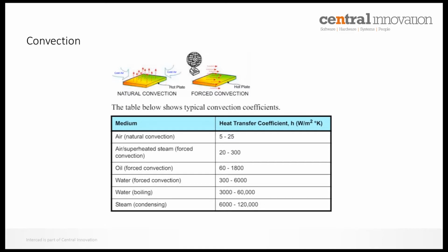In most engineering applications, when we need to cool down a certain surface or a certain body, we make use of a fan or a forced airflow or a heat pipe or a liquid flow, let's say a liquid cooling system, etc. What this does is it complements the natural convection system, and it increases the energy transfer rate from the solid surface. As I told you before, in the Simulation Professional suite, the thermal analysis module does not have the functionality to calculate or simulate fluid currents, but it can take into account the effect of fluid currents in terms of a heat transfer coefficient. To make things slightly easier for you, SolidWorks has provided some experimental data to be used to simulate this sort of scenario.